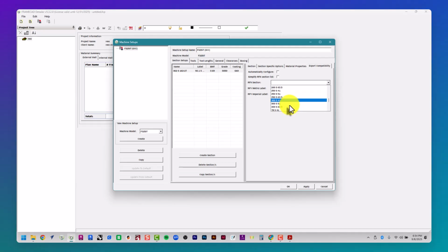This is one option that we'll have. Now we just need to add a couple other ones that use a different thickness. With our machine here, we typically run 20 gauge material, but I can run as thick as 18 gauge or 22 gauge. When it comes to gauge, the higher the number, the thinner that material actually is. So 18 gauge is thicker than 20 gauge, and 20 gauge is thicker than 22 gauge. So 22 is actually the thinner one.